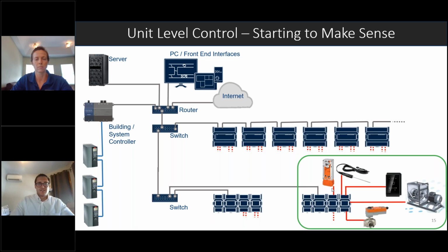If it's a new installation, there's no existing infrastructure to build off of. BACnet IP offers the security and the speeds that are going to carry your control system for the next 15 years, however long you have that control system installed for. That's one thing people kind of forget about, is how long these systems can remain within a building. You don't want to go with an MSTP system that's likely already 10-plus-year-old controllers that have maybe seen a few minor updates. The IP product lines are definitely the newer ones with every BAS manufacturer.